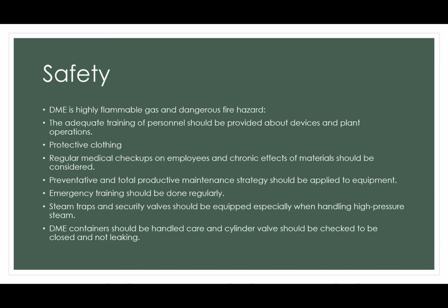Preventative and total productive maintenance strategies should also be applied to the equipment. Emergency training should be done regularly. Steam traps and security valves should also be equipped, especially when handling the high pressure environment that this is or could potentially be. DME containers should also be handled with care, and a cylinder valve should be checked to be closed and not leaking, as DME can be harmful to people in the environment.